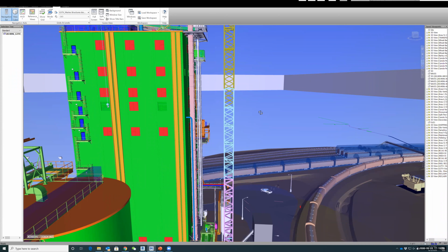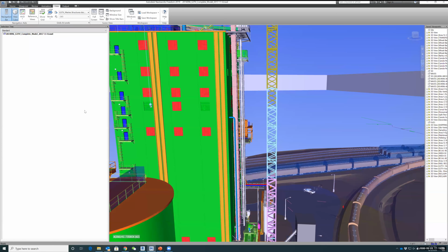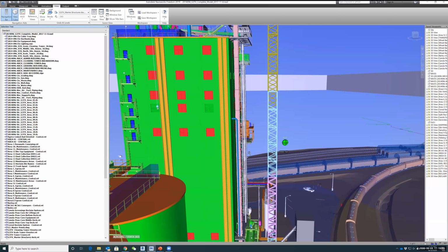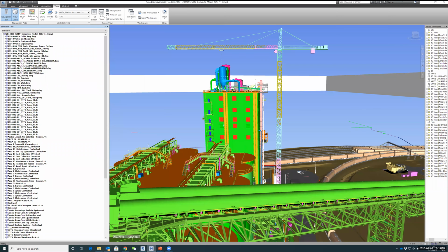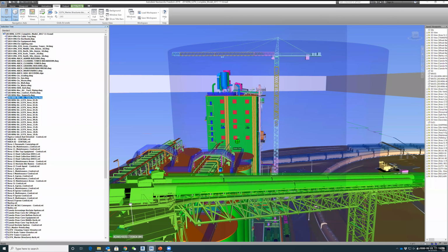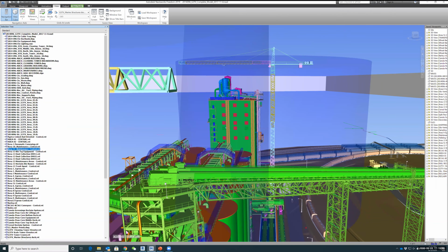You'll find 10 of them. So when you run this clash detection, you don't run everything against everything. Just pick, you know what, I want to run the second level of this building, the mechanical system on the second level. And let me just open this selection tree, make it bigger. And also the structure of that, how to do it. If you open this one, see, it's like a selection tree, right? You select that, it will highlight what you are selecting. So now you can basically know what you are doing, what you are trying to connect, right? So this one highlights everything like this.